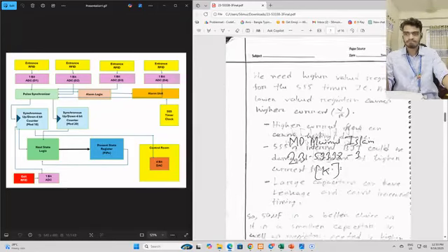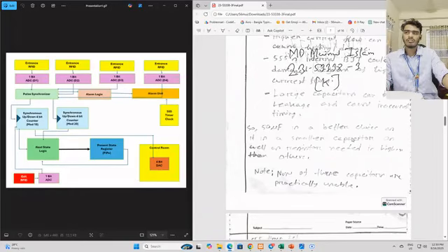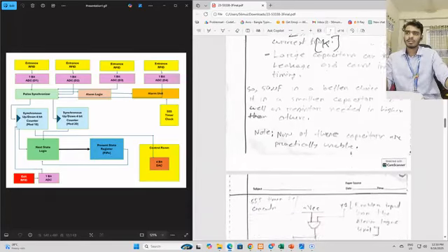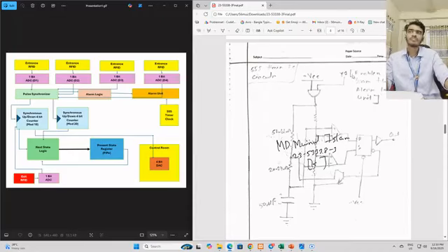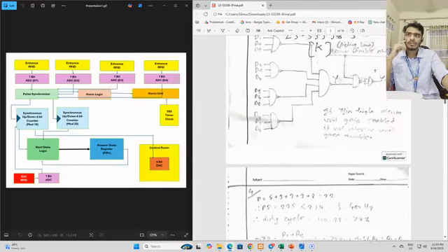Practically, all of these combinations are not fully usable, because these are very small capacitors, so we will have issues on that. With that capacitor and those resistors, we have designed this 555 timer circuit. See the Y1 signal. We got this Y1 signal from the manual disable switch.